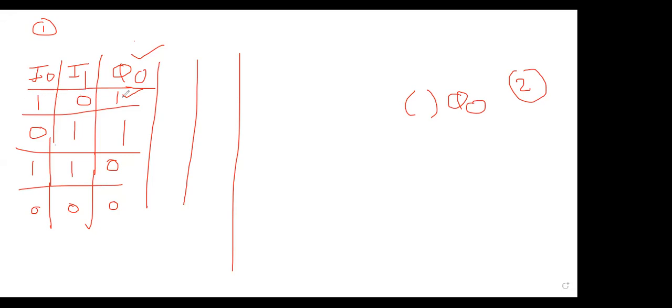Once more. Check the true condition of the output. Add the status of the inputs you have used. And what is the status? 1, 0. So for input 1, what did I tell you? For input 1, you take NO. For input 0, you take NC. And what is the address of this one? I0. So I take I0. What is the address of this input? I1.